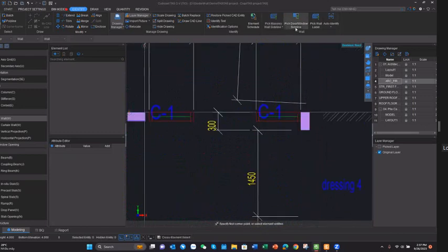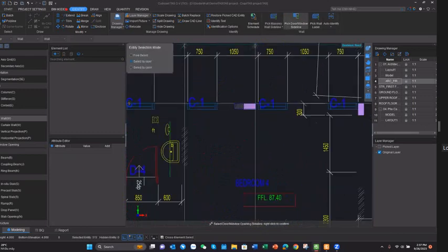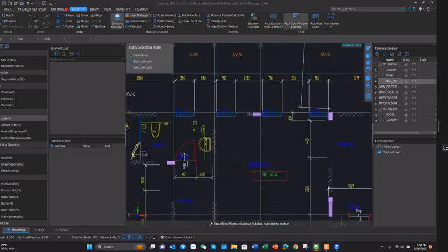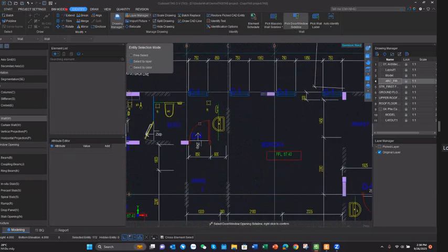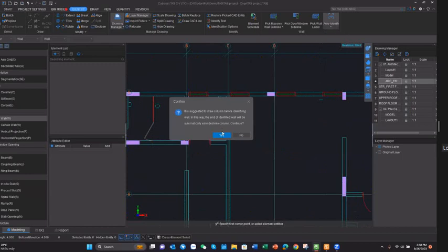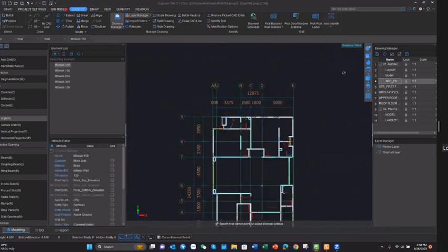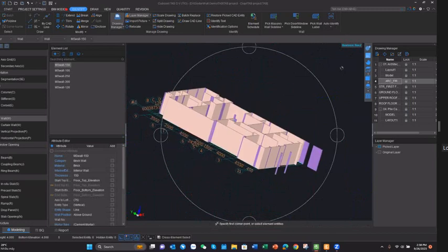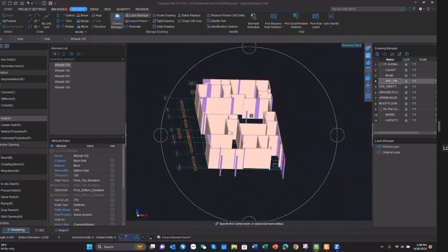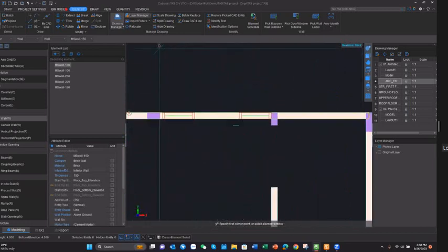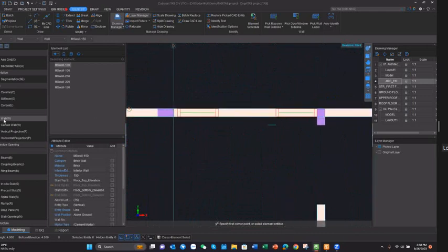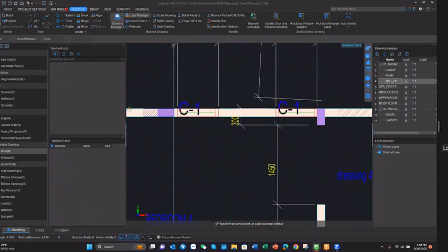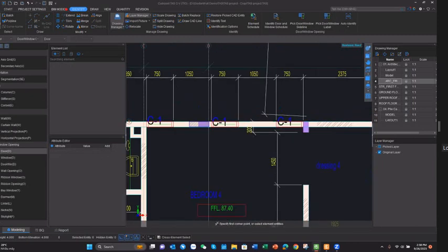And after that, I did door and window align because above door and window we also have wall column, and then I just click auto identify. So now on wall automatically identify. And in this step, we already built door and window highlight, but we don't have the door and window information. So we will move to the door and window and add the information of door and window to software.